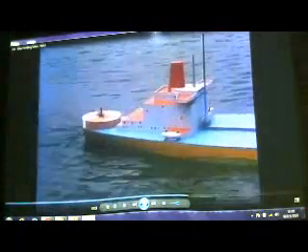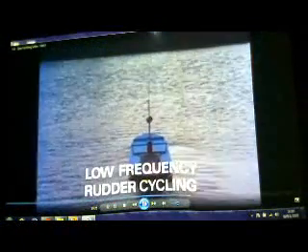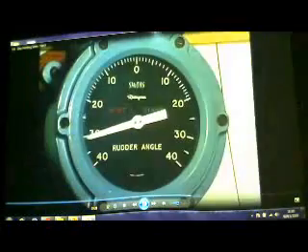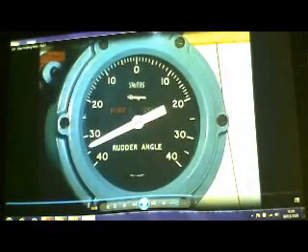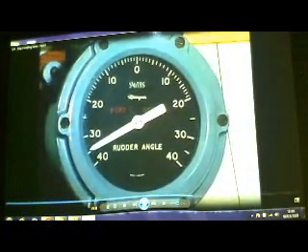Forces other than astern power can be used to retard the ship. The hydrodynamic drag, part of the resistance to forward motion, can be increased by moving through the water at a drift angle. A maneuver which benefits from this increased drag is called low-frequency rudder cycling. Here, in deep water, the rudder is initially put hard to port, and when the ship is about 40 degrees off course, the rudder is reversed. When crossing the initial heading, the rudder is returned to hard to port.